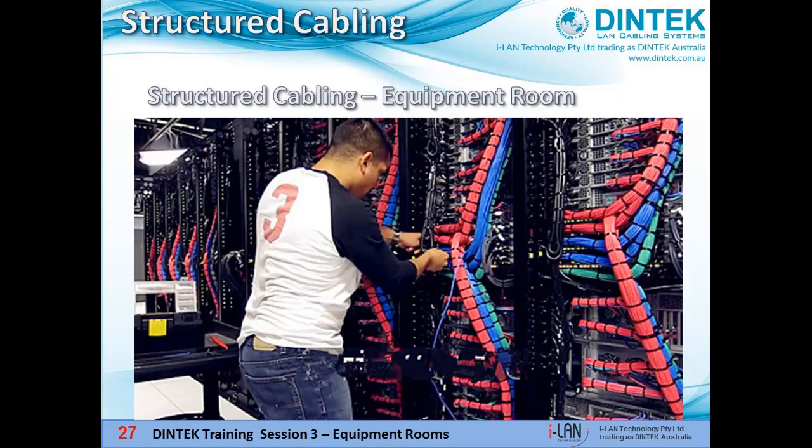And then there's the other extreme. This looks awesome, but some cablers won't like it at all, and it also goes against standard TIA 568C.0, which states that cable stress, such as that caused by tension in suspended cable runs and tightly cinched bundles, should be minimised. Cable bindings, if used to tie multiple cables together, should be irregularly spaced and should be loosely fitted, that is, easily movable. A rule of thumb is you should be able to spin the cable tie around the bundle. These cable ties are clearly too tight.